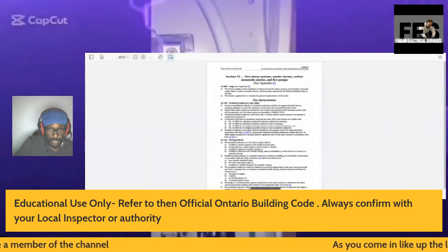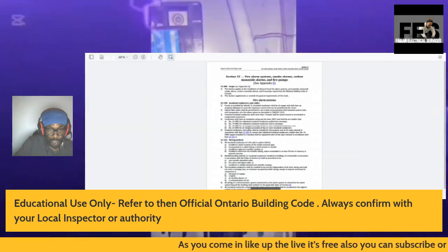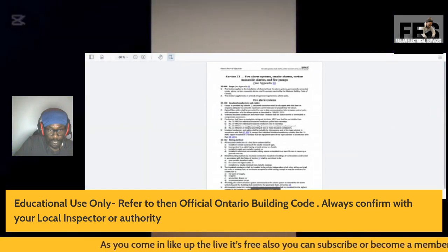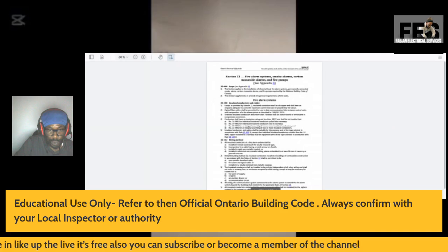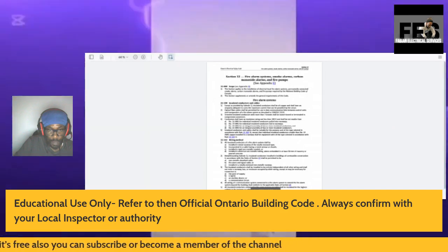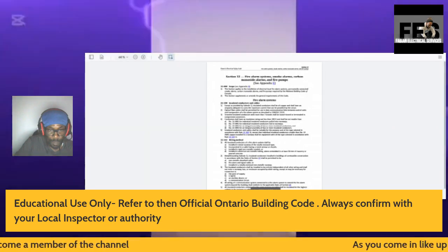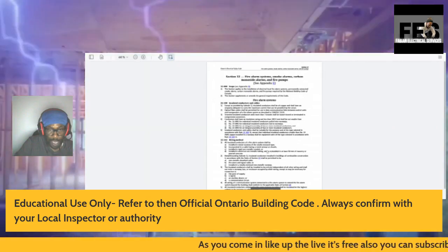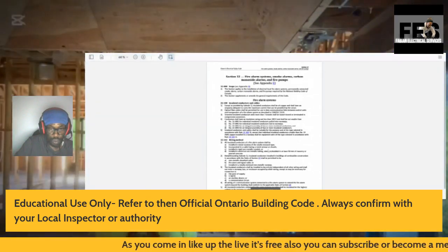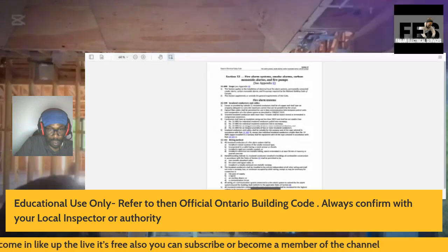Wiring method. An insulated conductor of a fire alarm system shall be an insulated conductor of a fire alarm system type, a cable having a metal armor or sheath. The trade name we call it is BX, aluminum sheathed cable is the name.